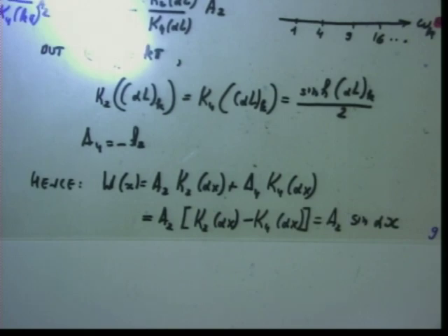Yes, so what happens is that the mode shape equals A2 times sine alpha x. Now, what is the conclusion? First of all, one conclusion is that mode shapes depend upon some constant, A2, which is not determined. We did not determine it, but we solved everything else. We found natural frequencies. There are an infinite amount of them. The mode shape is not uniquely determinable, which is understandable, as we know from eigenvalue problems.